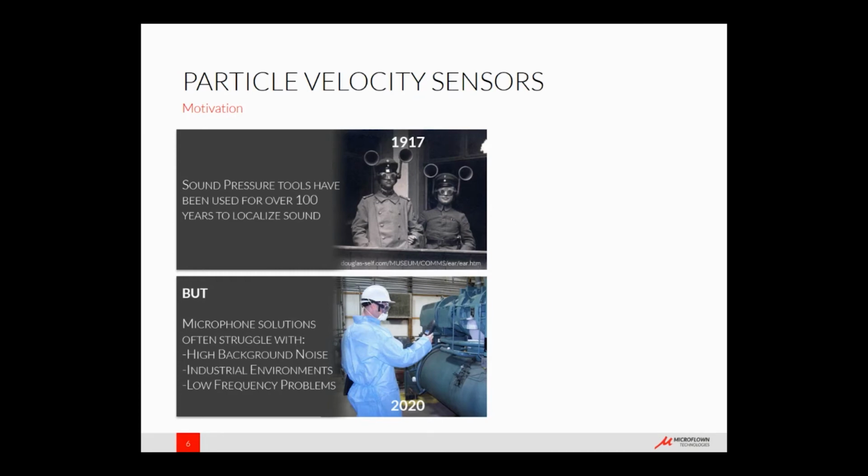If you look at really low frequencies where you have very long wavelength, if you're using a scalar value that has no information about direction, it can make it difficult. You have to use a spatial distribution of sensors in an array of microphones. You limit the operational frequency by that.